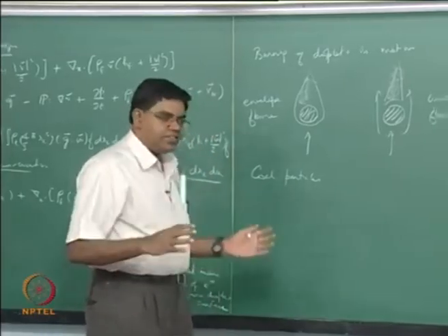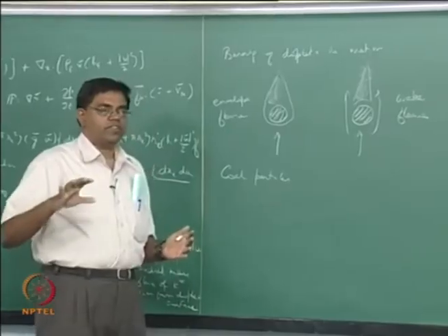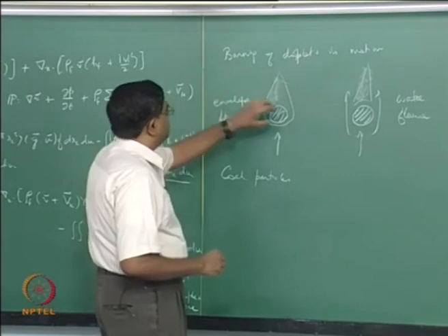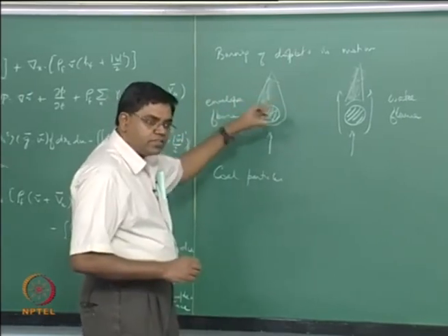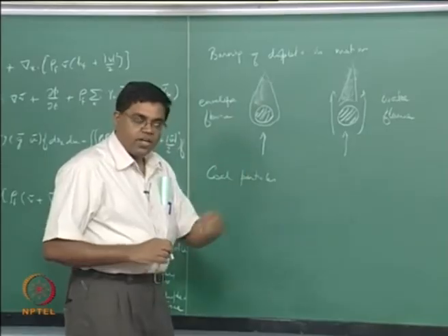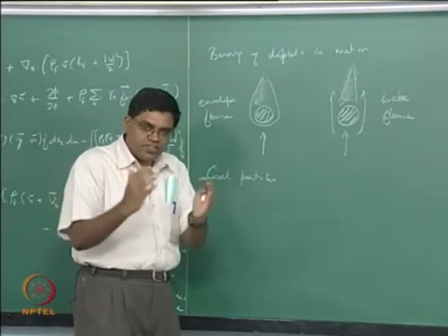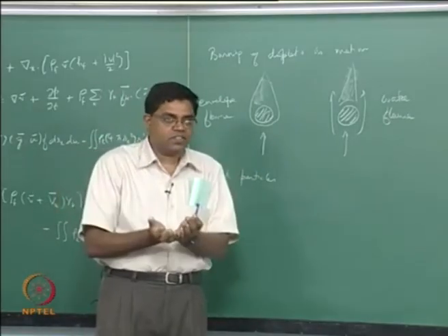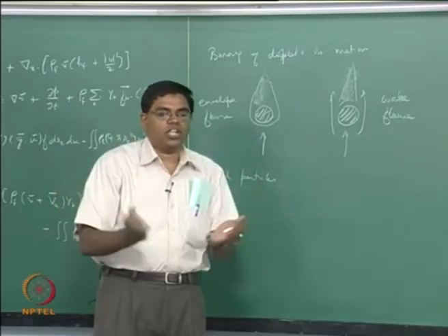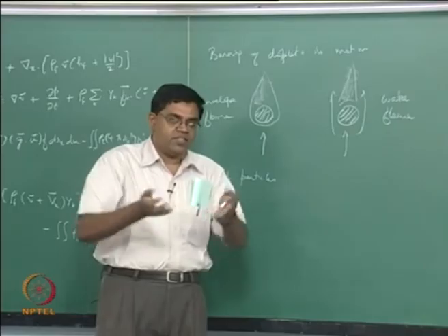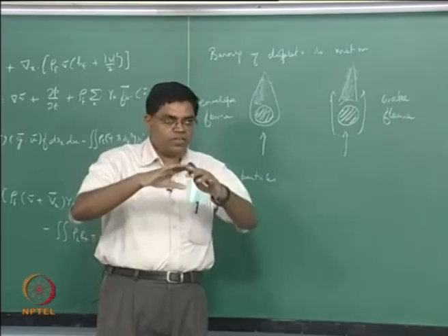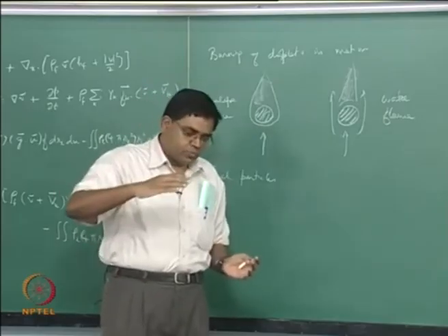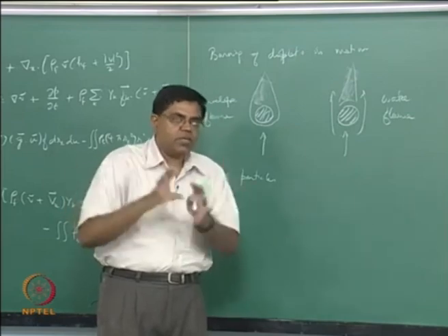So what happens in these kinds of situations, where you have a mixture of materials of different volatility, is the less volatile substance will begin to accumulate on the surface as the surface is regressing, right. As it accumulates and the surface is shrinking, the density of the less volatile substance increases, and it begins to form more like a shell. For example, in the case of aluminum, it could even get sintered together like a shell, and when it's sintered, it's like a porous structure through which the more volatile substance gets evaporated, right.